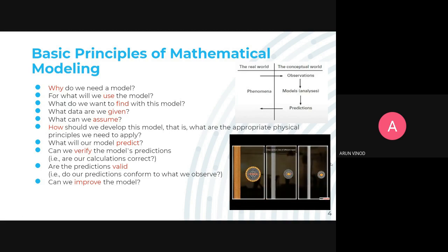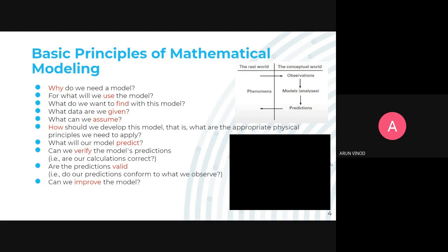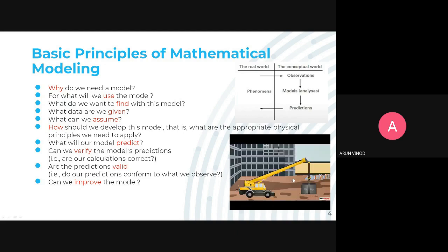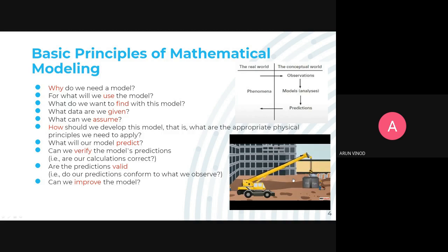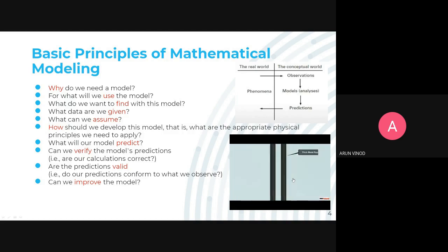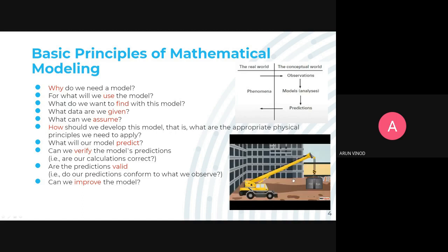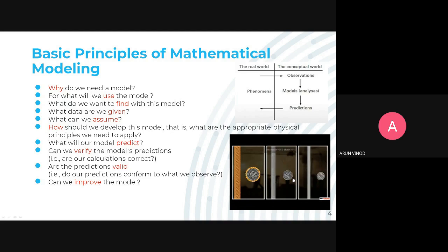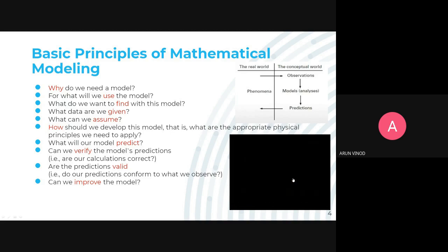See, this is the cross-section view of different ropes. The cross-section of the rope is defining the elasticity of the rope. But you have to calculate the elasticity. Even though it is fine for 750 kilograms of weight, for example, if you increase the load to 1500 kilograms, sometimes this elasticity is not enough. So you have to calculate that elasticity also.